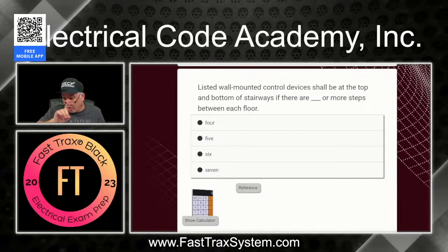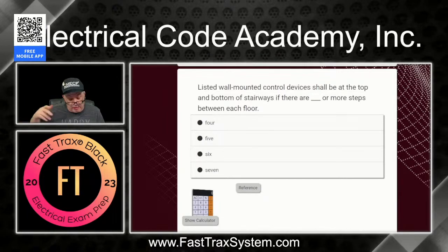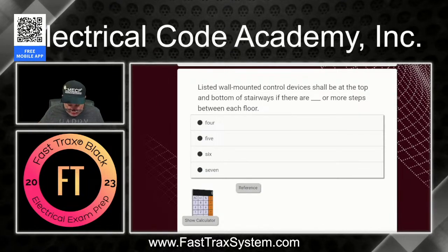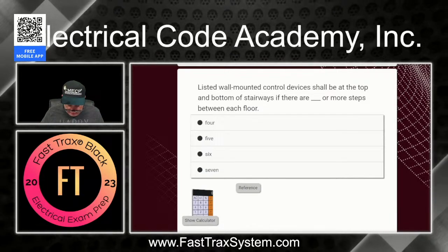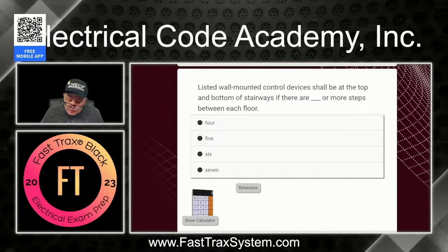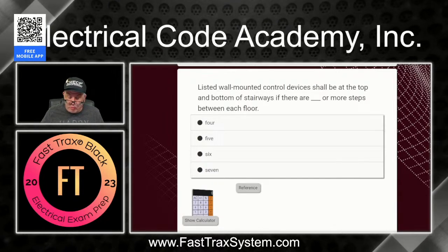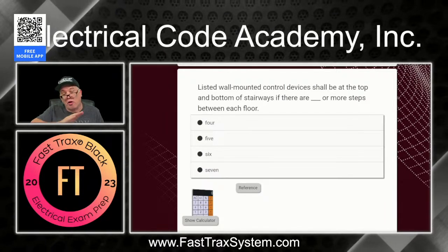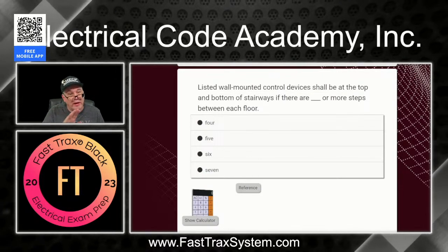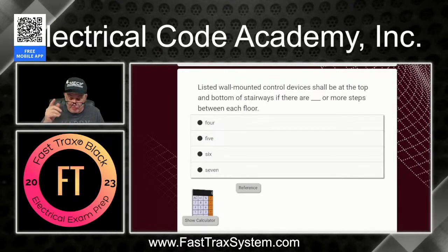And remember, outlets are not the devices you put in the outlet box. Outlets are a location which you put devices into. So we look at outlets and we kind of go down here and we look at required outlets. Okay, so we know the required outlets are in, let's say, this stairway, and we know that the switching aspect of it is based on the number of steps.